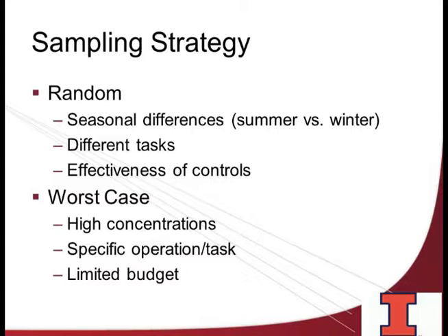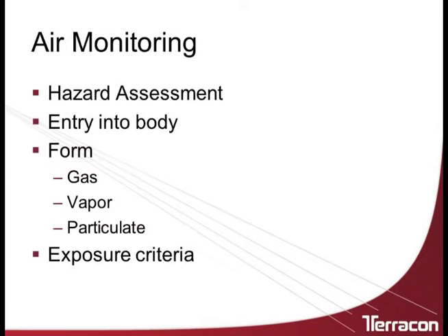When we talk about air monitoring, there are some items that I'd like to go into a little bit further. One is the hazard assessment, the entry into the body, the various forms, and the exposure criteria. This will dictate just exactly what and how you're going to go about the sampling approach.